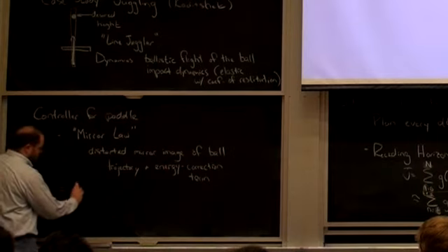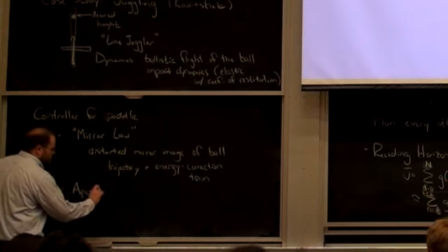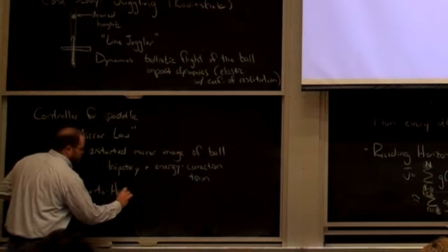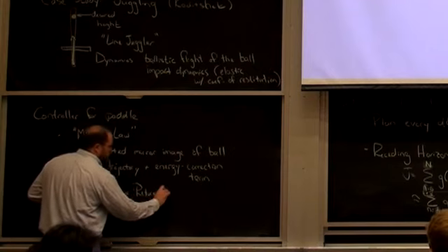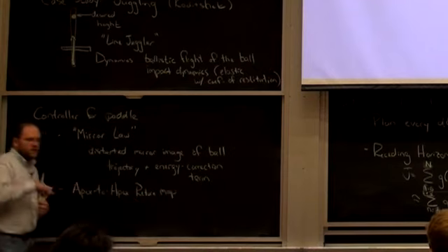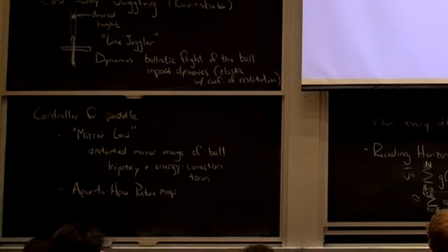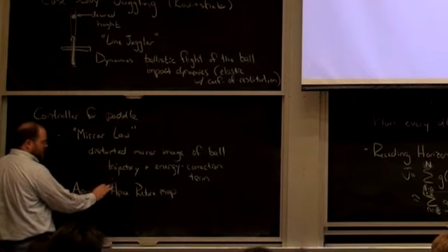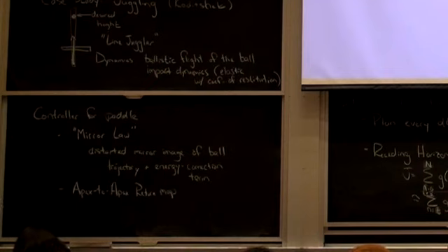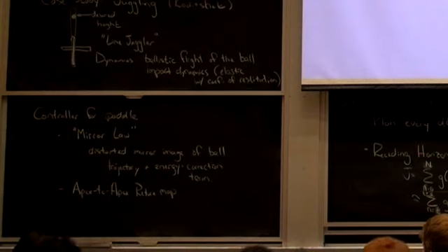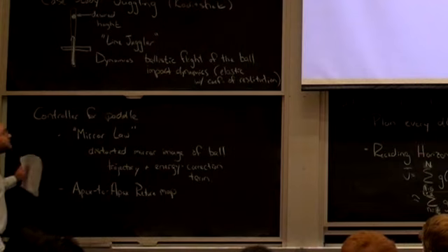They do an apex to apex return map, the same way we did for the hopping models and all the other models. These guys were pushing the unimodal maps and getting some global stability results out of that. That's why I think they had a global result. So it's exactly like a hopping robot, just the ball's moving instead of the robot.